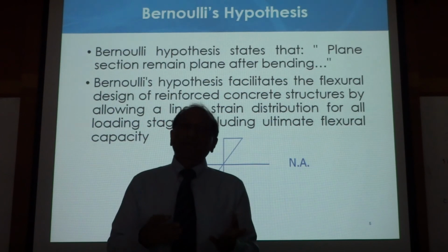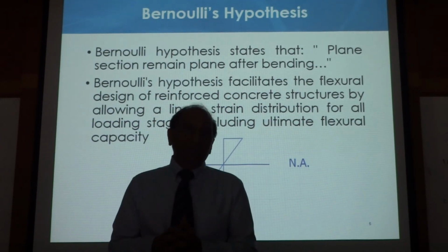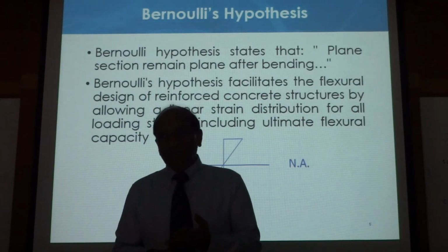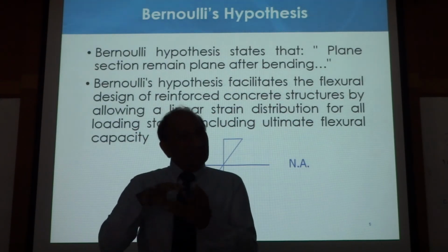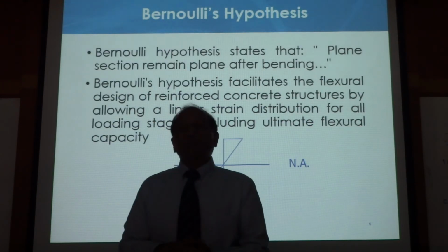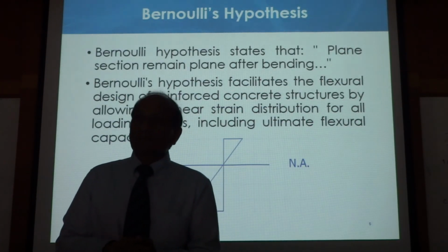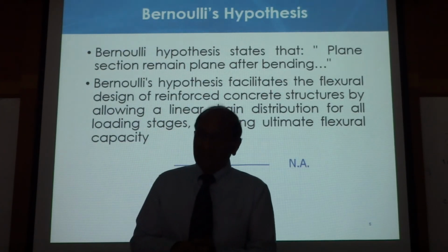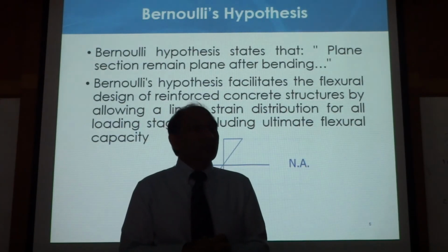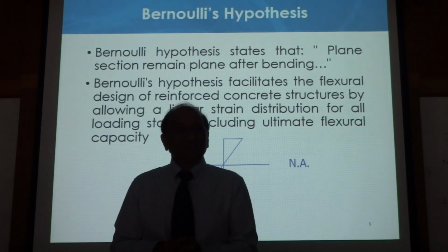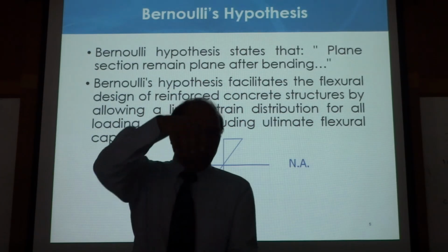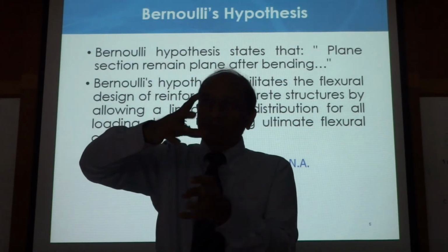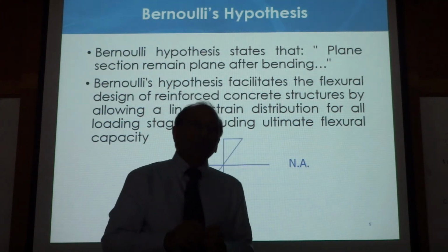And we also said that, okay, that is not really true because there is some warping, and warping is of a different kind. And also there is crippling. Many other modes also happen. For example, what is crippling? Do you know what is crippling? No, not buckling, really. Anybody knows what is crippling? If you take a piece of paper and you press it, it becomes wrinkled, right? It's not really buckling. It becomes wrinkly, and that is called crippling.